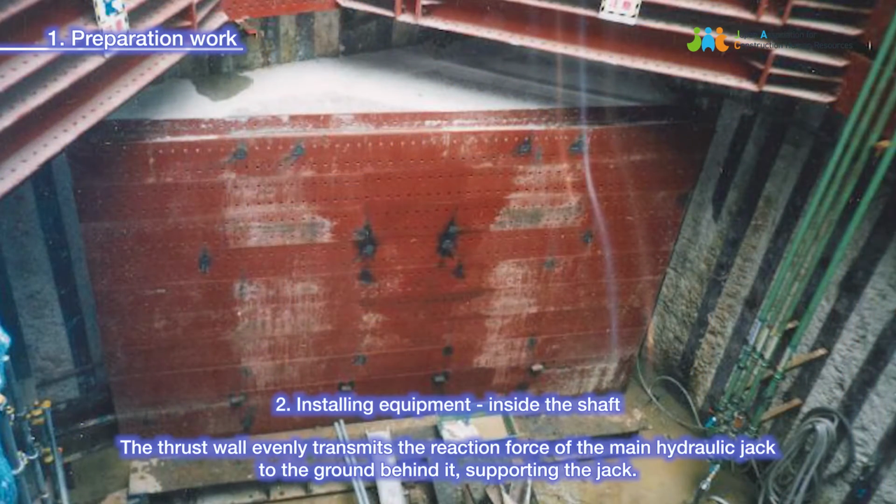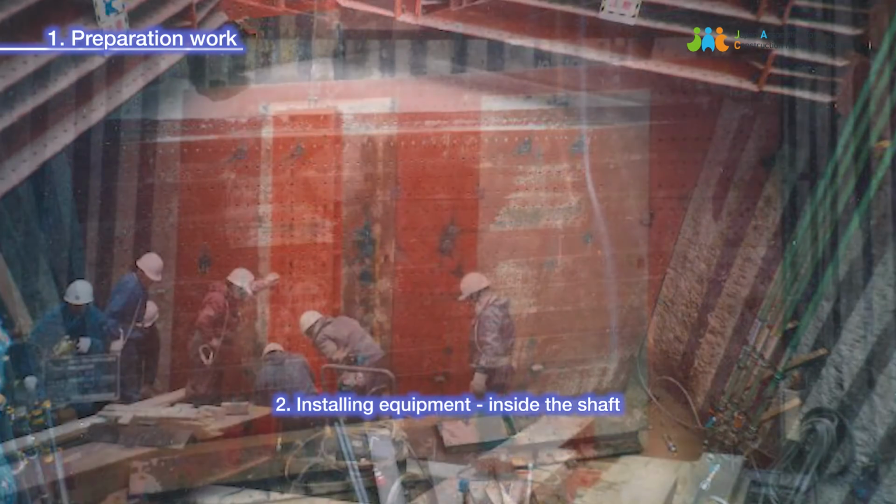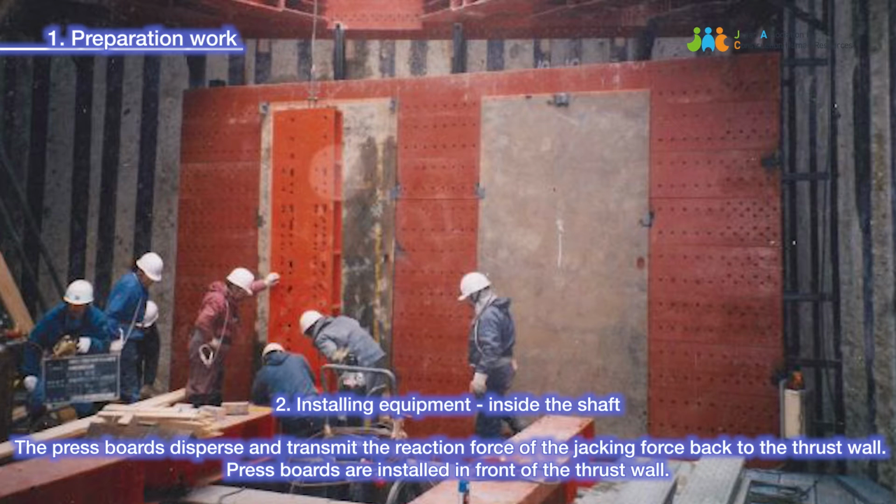2. Installing equipment inside the shaft. The thrust wall evenly transmits the reaction force of the main hydraulic jack to the ground behind it, supporting the jack. Construct by pouring concrete using formwork. The press boards disperse and transmit the reaction force of the jacking force back to the thrust wall. Press boards are installed in front of the thrust wall.